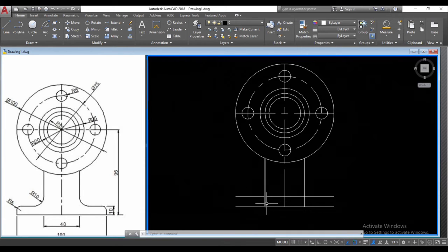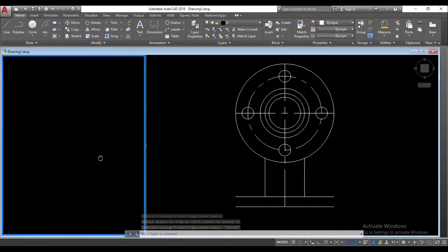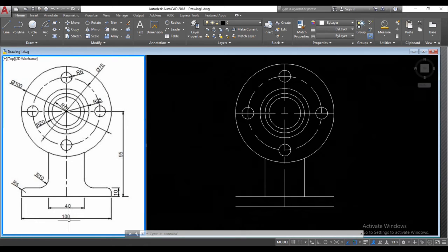So we have some lines here that we are not needing. We're going to trim, and we can select trim from the extend command, press enter, and just trim this part and this part, right? Again, we want to look over here. We have a line of 100, so we know that from this line we could offset 50 here and 50 here.